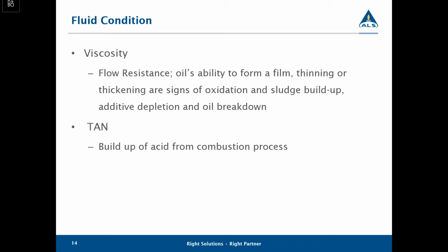For total acid number, buildup of acid from combustion process, you really want to keep your eye on that. Obviously, when you're doing extended oil drains, you're always going to try to find that balance of not allowing too much acid buildup to occur.